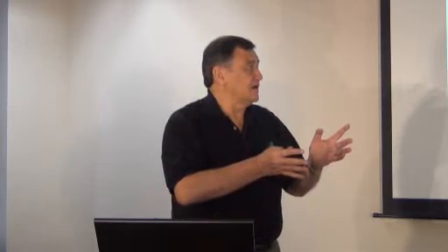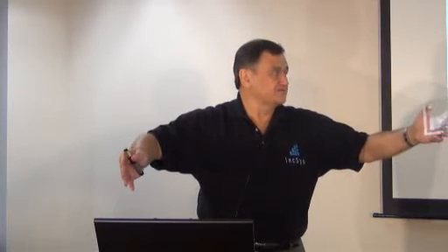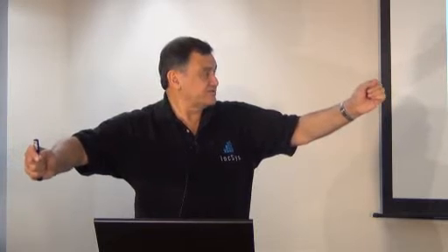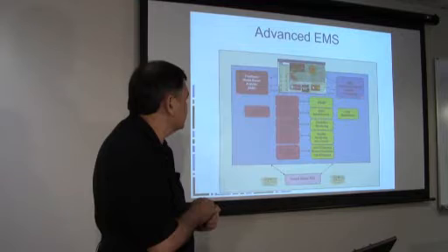It's just recently that we've had very accurate satellite clocks that can synchronize the power from one substation to another, down to microseconds. That high-speed accuracy of knowing exactly the time at that substation allows us to calculate the number of microseconds between the crossing zero here and the crossing zero here. And so for the first time, we have been able to monitor that value and display it to the operator. And we actually display it at a rate of 30 times a second.